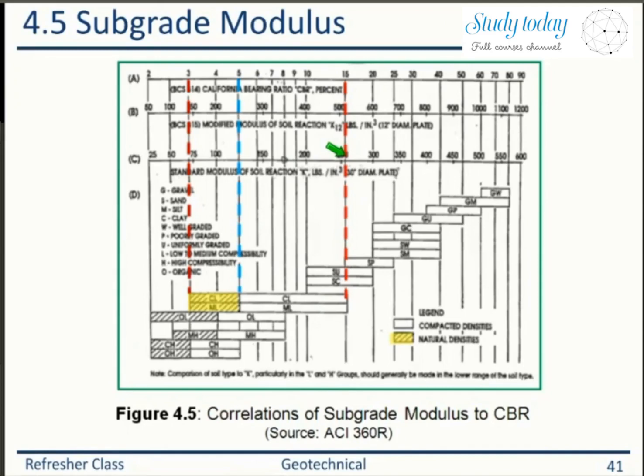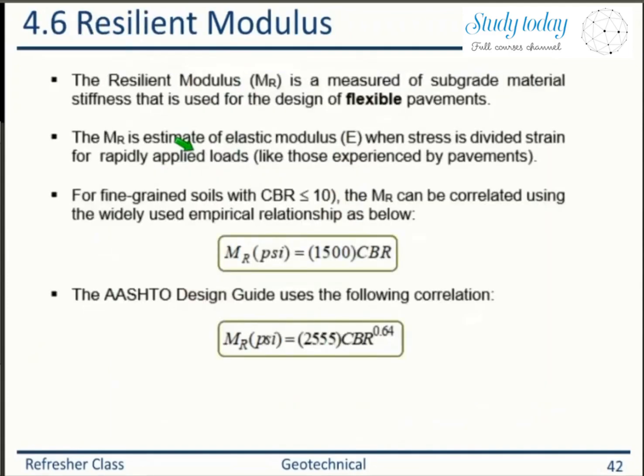That's why we perform compaction of the soil at an actual construction site, because that will save you a lot of money. Okay, because you have improved the ground. How can you see it? You can see it because the value of CBR as well as the subgrade modulus k will be increased. If these soils are to be used as a subgrade material for the roadway pavement, your roadway pavement will be very, very strong if the soil is compacted. And these are also interpolated values, right? So depending upon soil type, you can see it here.